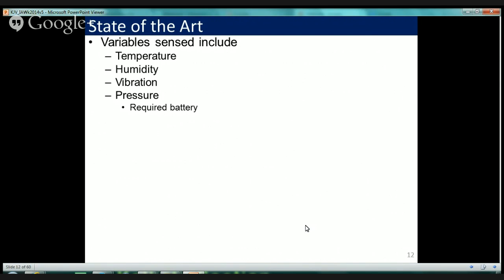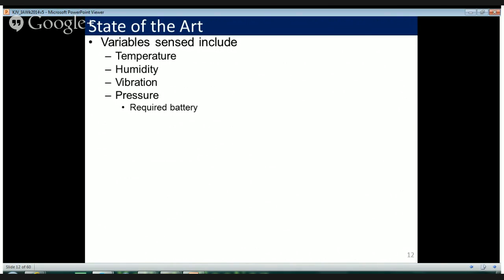But although we say RF energy harvesting, as I said a little while ago, the power required to operate these are so high that you don't normally have such amount of power available easily in the ambient. So in effect, to make this work, you basically need to intentionally generate the RF power at sufficiently high energy density so that these could work.